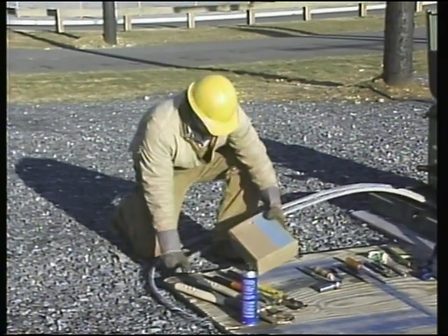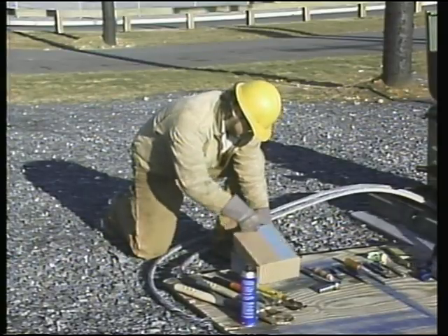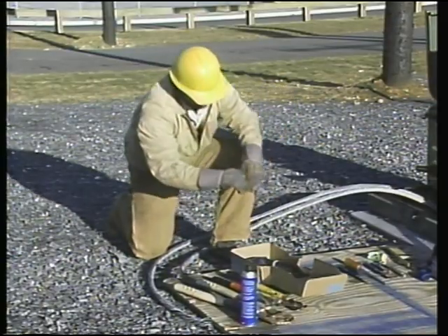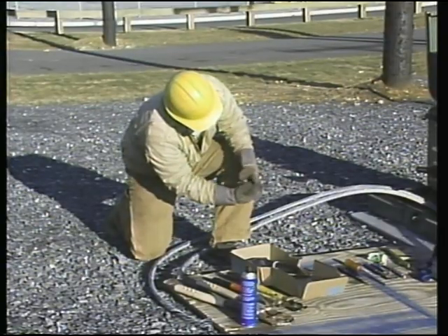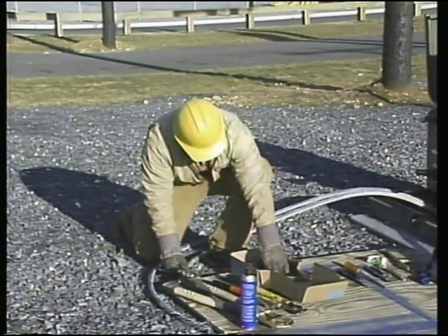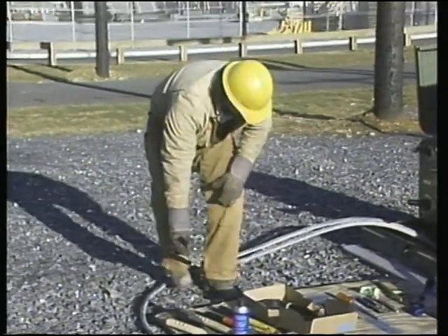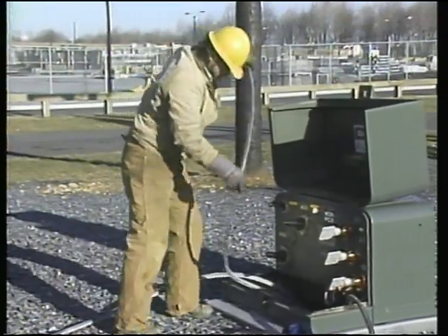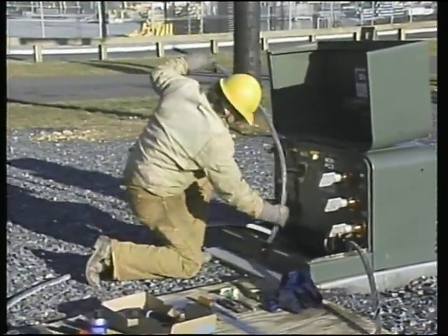Okay, now that we've seen how the two types of elbows are constructed, let's watch as a load break elbow is prepared and installed on a typical URD pad-mounted transformer. The elbow will be installed on a cable with a concentric wire metallic shield. The workman first checks the elbow termination kit to make sure that it's the right one for the cable it will be installed on. He'll also make sure that the connector provided in the kit is the correct size for the cable he's working with. Once he's determined that he has the right kit for the job, the worker trains the cable, leaving enough slack in the cable to make the termination.